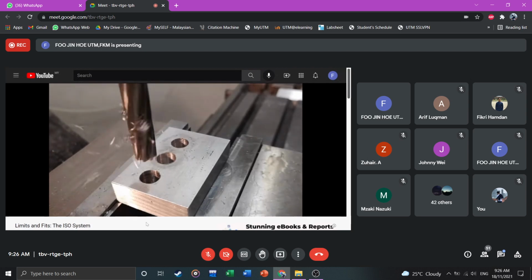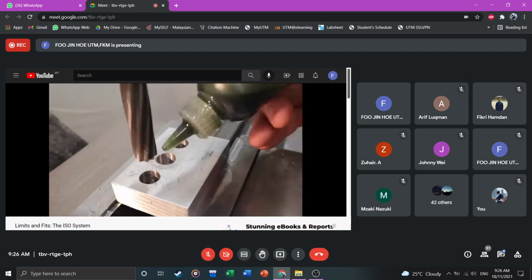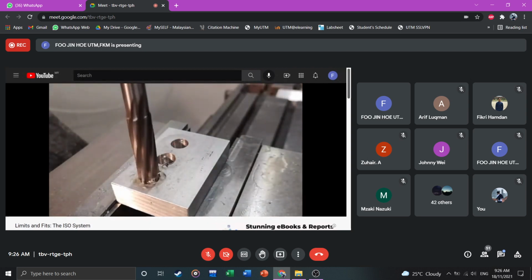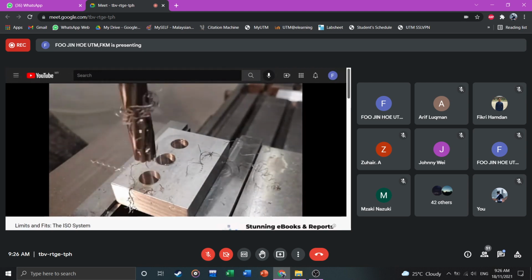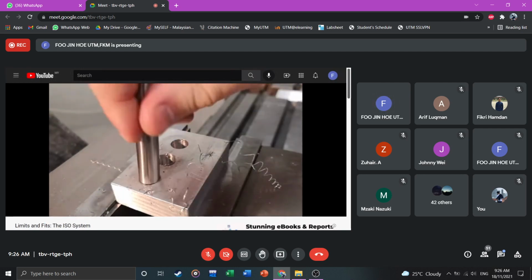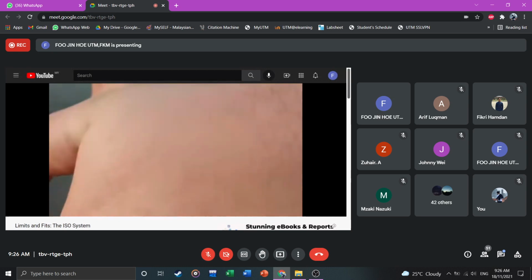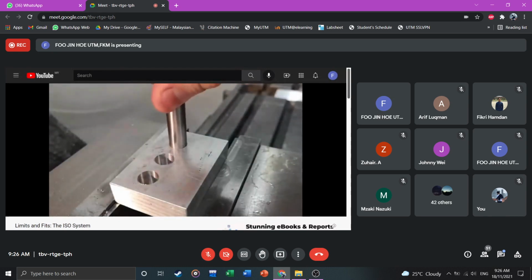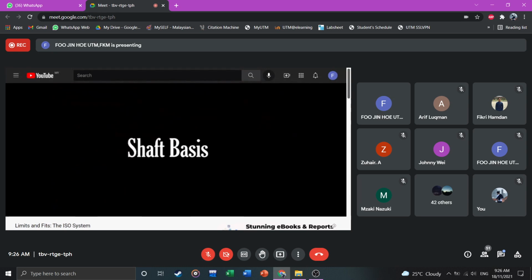The problem arises when you have a bag of 100 dowel pins and you have to ream 100 holes. Dowel pins have a tolerance on them, and their sizes will always vary a bit. Your reamer will also cut slightly different sized holes, depending on your work holding, wear in the reamer, and the cutting parameters, all of which can change while reaming your 100 holes. Because you bought the dowel pins and have no control over their tolerance, this is called a shaft basis fit.